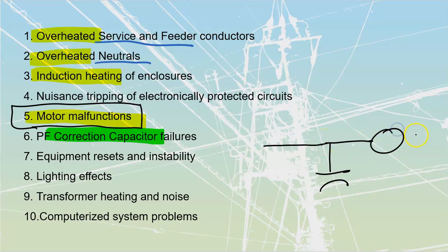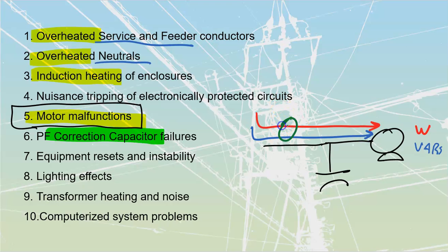We've got our loads that are going to be downstream. We've looked at this the other week or whatever, where we talked about what power factor correction itself is. If I've got a motor that has a VARs demand and has a watts demand, we'll just draw it like this. So I've got watts and I've got VARs. What I'm usually going to do is supply both of those from the source. And so here's my incoming. My source will supply the VARs and it will supply the watts. Together we call that my VA, the vector sum of that, right? We just add it up into a triangle. We call that the VA.